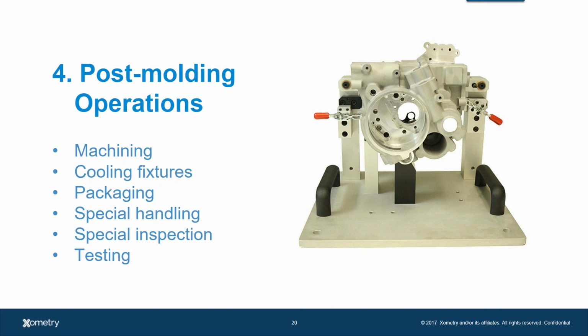Yeah, and it's really important also to know where that cost drives in. So when we're looking at some of those things that change the surface of the part, or for example, what type of metal we're choosing, that's going to be on the actual tool itself. That gives you that higher upfront tool cost. But post operations are manual touches of that part, and that's going to give you a higher per part cost.